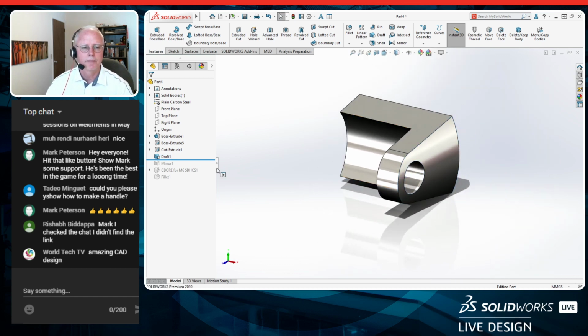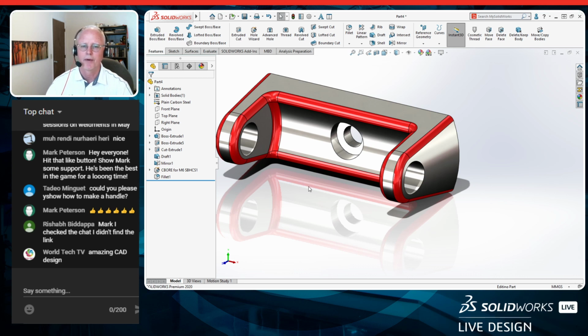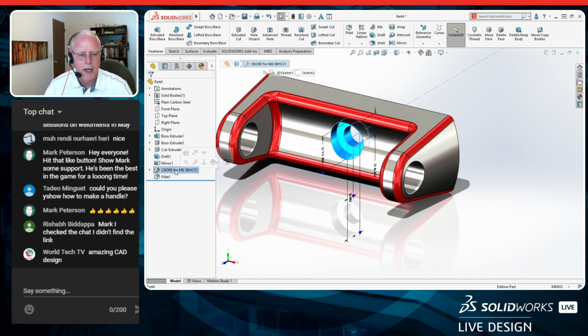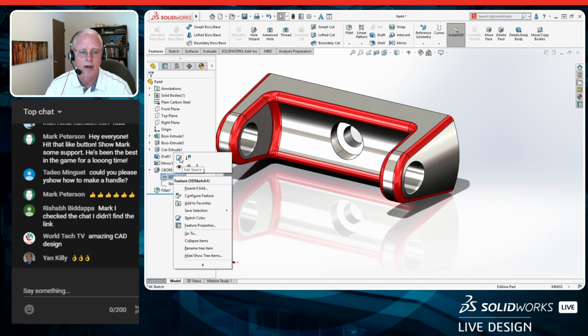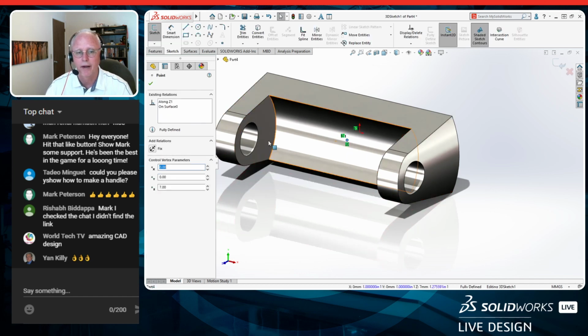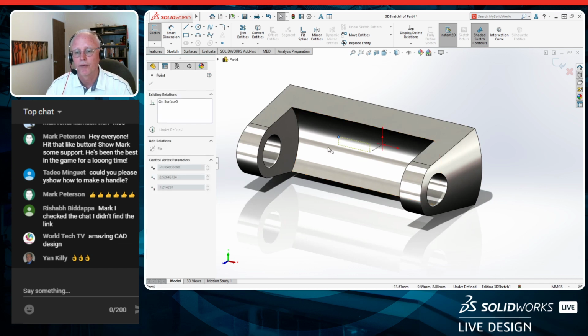All right. Now let's do the counterbore holes. Let's get that out of the way, and then we'll come back and show you a couple different techniques for adding that draft to the side face there. Counterbore hole. So I'm just going to go straight in and edit this 3D sketch. So that's the position, the 3D sketch. So remember before we added an along Z relation there. Got to keep the on surface. I'm going to delete the along Z relation. So now I can take this and move it around on that surface. It stays on the surface.